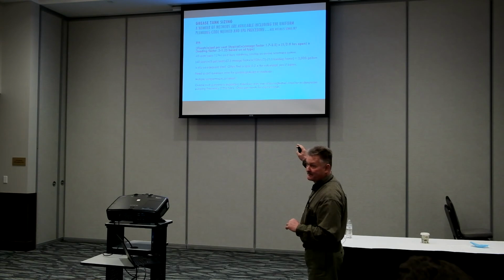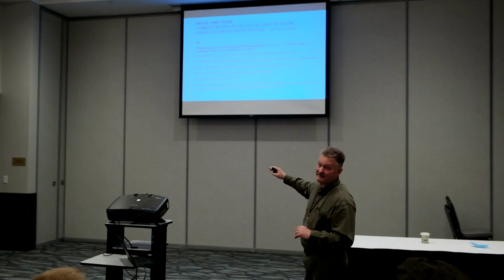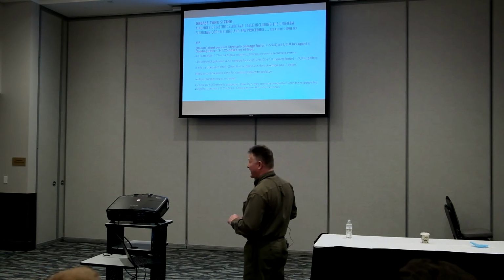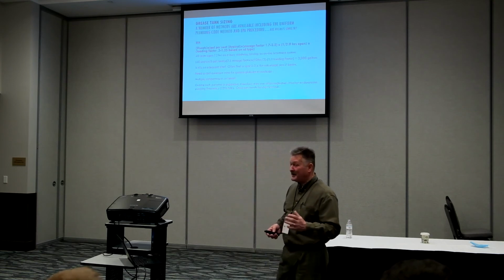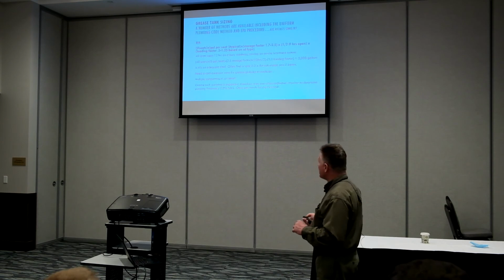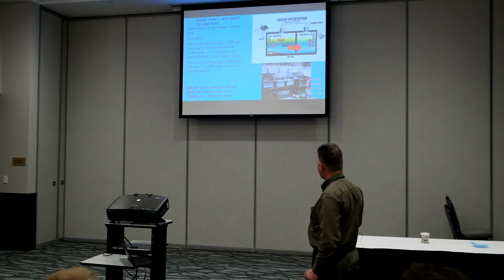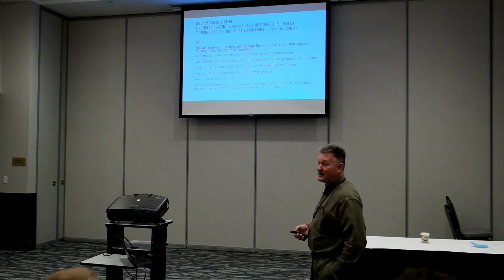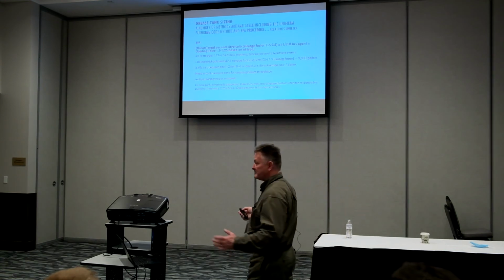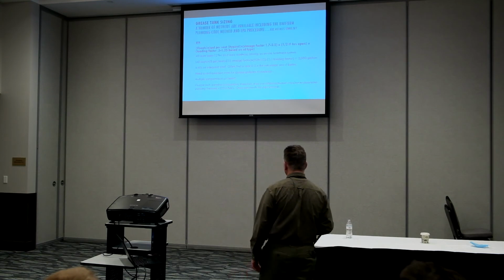No. Just like our references for waste strength and flow, you get 5 references, you're going to get 5 different numbers, so which one is right? Oftentimes a lot of these produce a design of about a 1-day detention time. It's not enough. So whatever you calculate, a good rule of thumb is to double or triple it. Create some safety factor in that system.